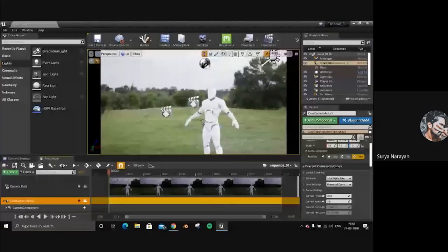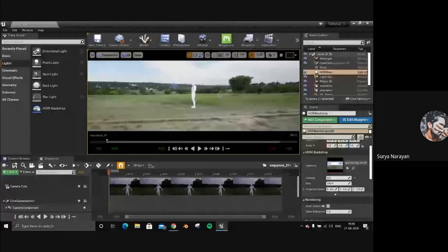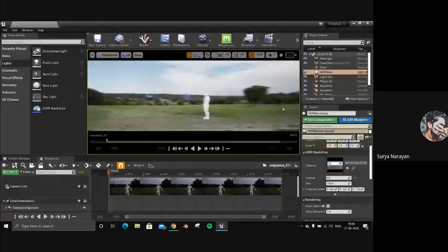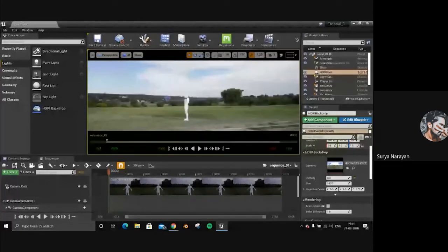And now we're going to switch to the cinematic viewport right here. If you click perspective, just down, and go from default viewport to cinematic viewport. Click that. So this is the cinematic viewport. We need to switch back to our camera view. This is going to be a little tricky because you have to really pay attention, as there are a lot of views. Now we're in the cinematic camera viewport. We're not looking through the camera. So if you want to look through the camera, press this icon right here. We're back looking through the camera.